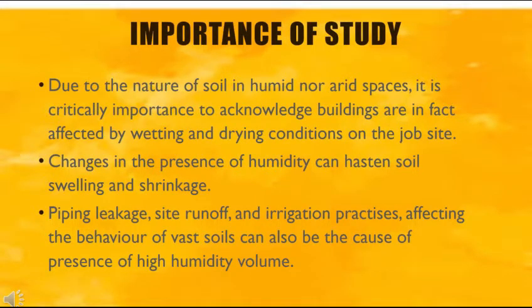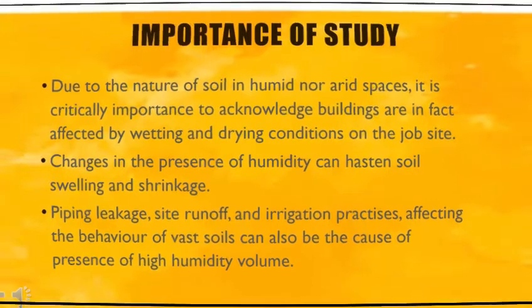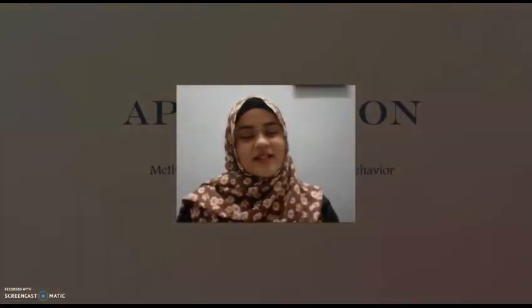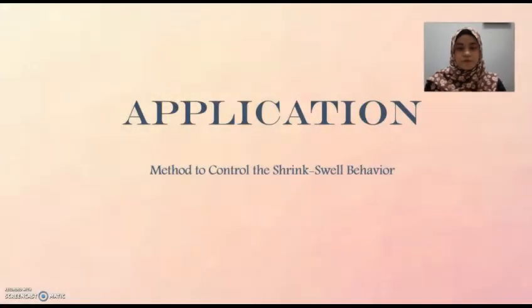Second, change in the presence of humidity can hasten soil swelling and shrinkage. And third, piping leakage, site runoff, and irrigation practice affecting the behavior of bare soil can be cause of presence of high humidity volume.